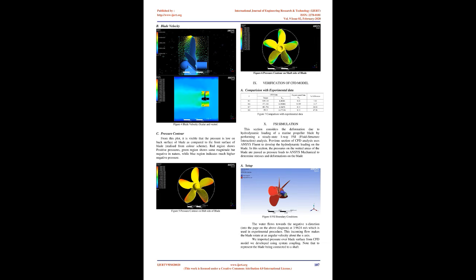We use the Reynolds averaged form of continuity and momentum and use the SST k-omega turbulence model to close the equation set. B. Boundary conditions. The input values from the experimental data, Emerson and Sinclair, 1967, have been converted to SI units. The values they used have not been specific, as they tested a number of different shaped propellers and stated only the cavitation number but not speed or pressure.